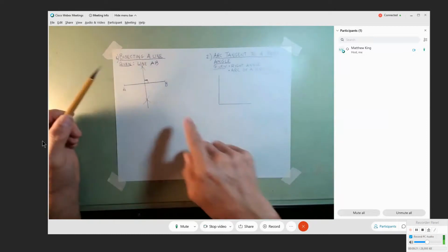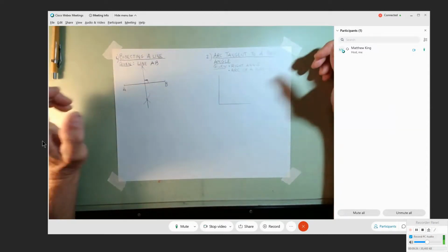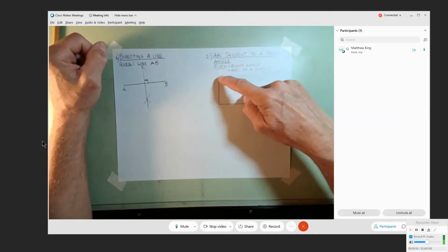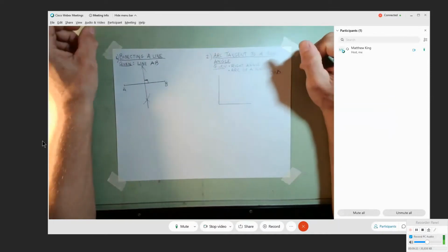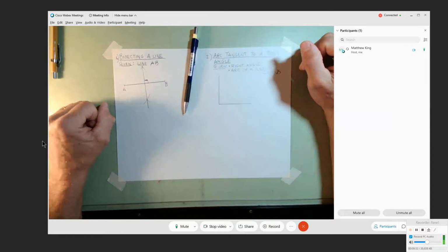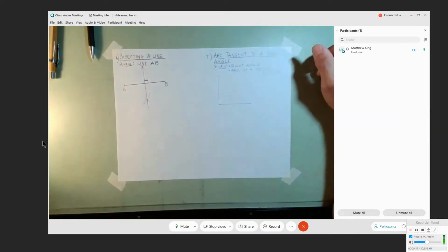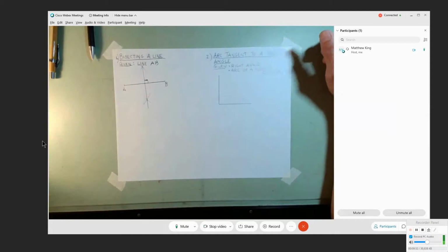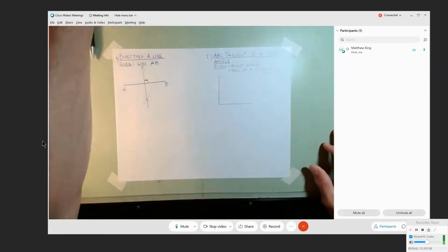I could use this first technique to get a right angle and go from there, but the other thing I want you to note is typically this would be very light. As I emphasized last week, when you start out your drawing, you want to always keep your 0.3 millimeter to do the layout. But for the sake of you guys seeing this, I'm drawing dark lines. But realistically, everything would be super light. All right, so there's my right angle.